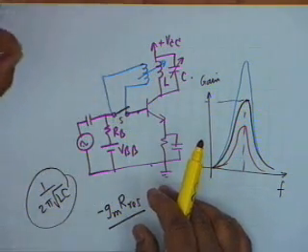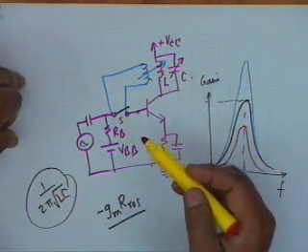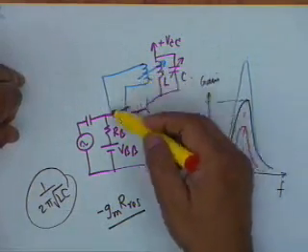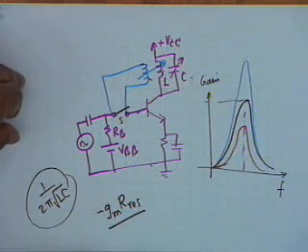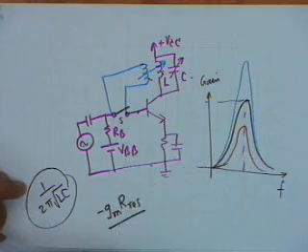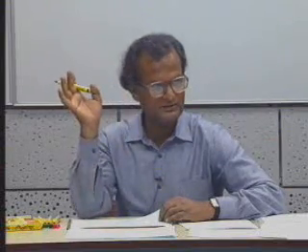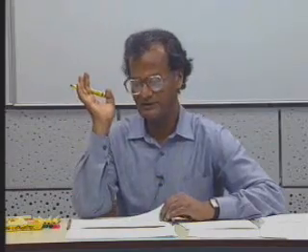H is the fraction of the output voltage. That will depend on the turns ratio between these two, all right. If this is 10:1, then 1/10 of the voltage would have been fed back to the input, okay. So, G is frequency dependent, H is not. On the other hand, there are systems in which G is frequency independent and H is frequency dependent.